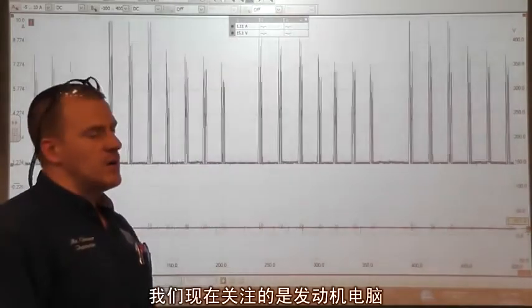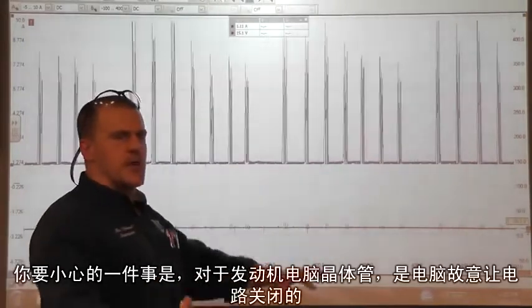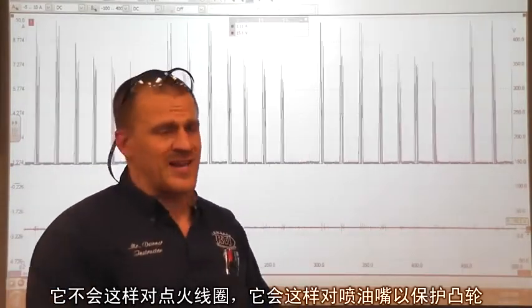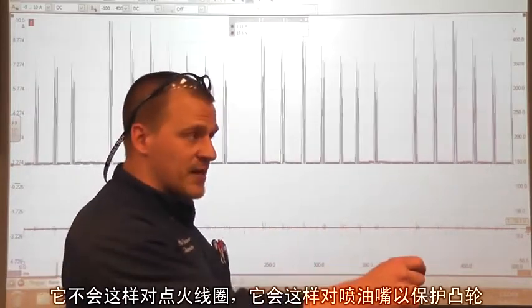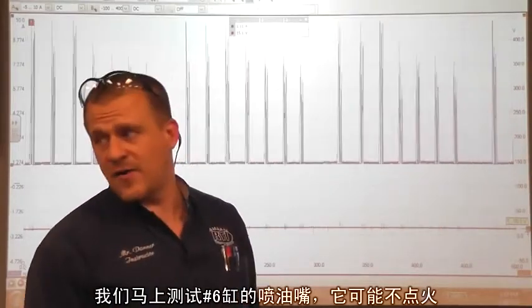Our focus is now toward this engine computer. Now, one of the things that you need to be careful of when it comes to an engine computer and a transistor is the computer shutting that circuit off intentionally. And from my experience, it does not ever do that with ignition coils. It does that with fuel injectors to protect the cat. In fact, if we check cylinder number 6 injector right now, it's probably not firing.